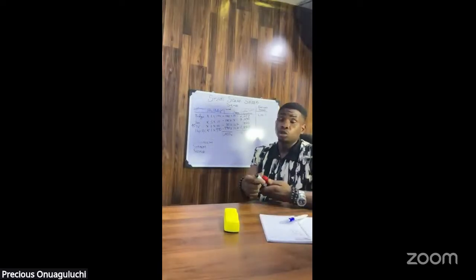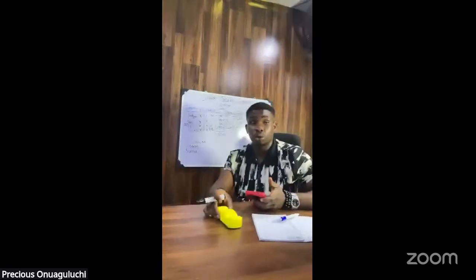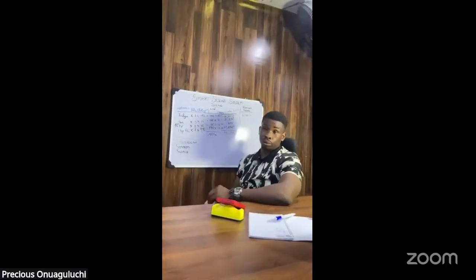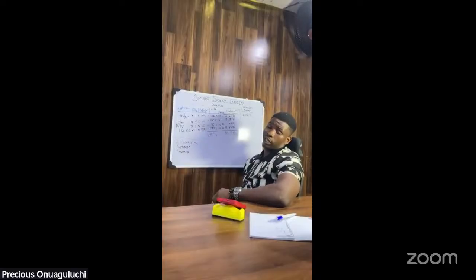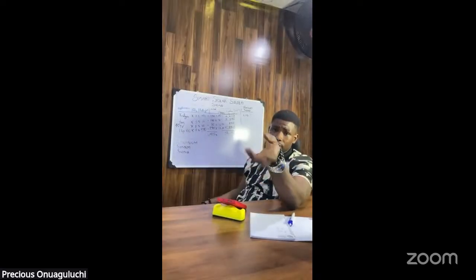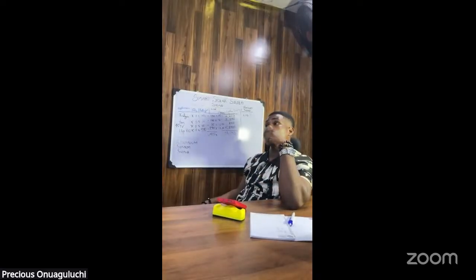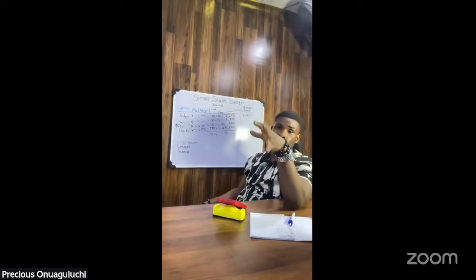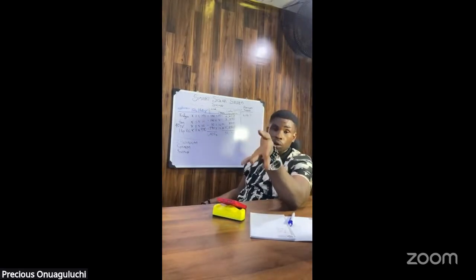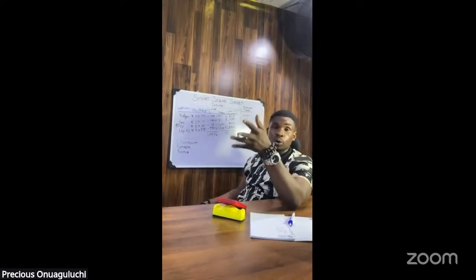Okay. So another important concept when you're talking about battery sizing is days of autonomy, right? A lot of times in our sizing, we neglect that. Days of autonomy means that if there's constant rain for 2 or 3 days, can your system serve? How long is your battery equipped to serve you, right?